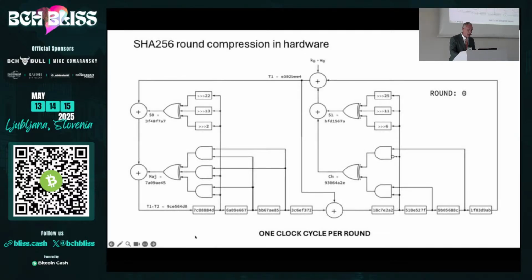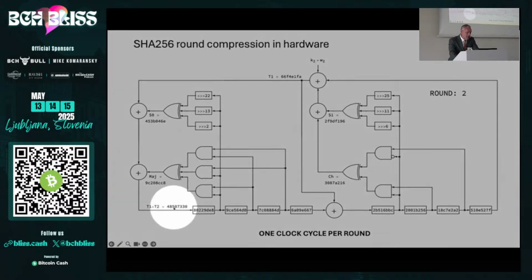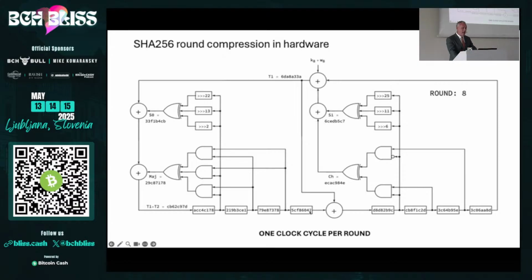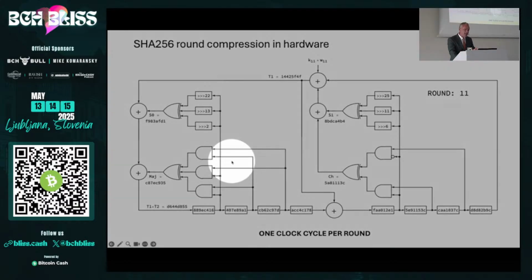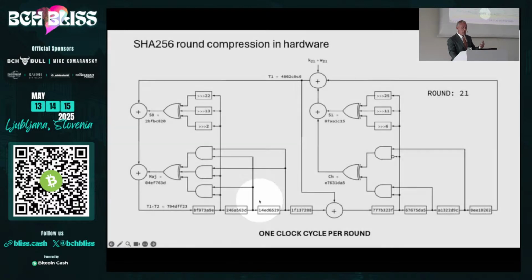into this register as soon as I turn on the clock. So I'll turn the clock on, and you can see this 48, 48, 48, 48. So it's just moving along every clock cycle. And as soon as the registers change, because they're wired directly to all these gates, the feedback term changes in under a nanosecond, which allows us to move through the SHA-256 computation one round of compression per clock cycle.